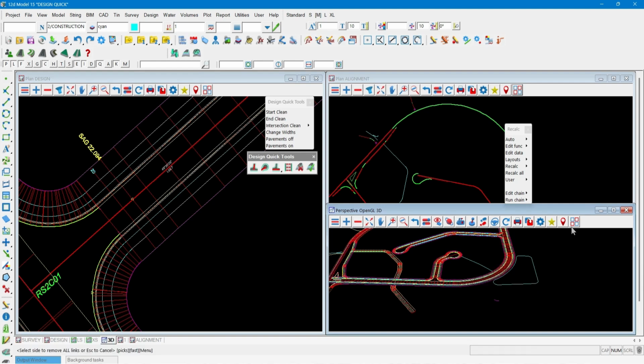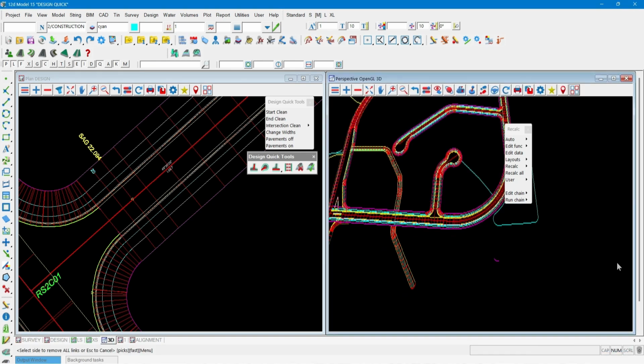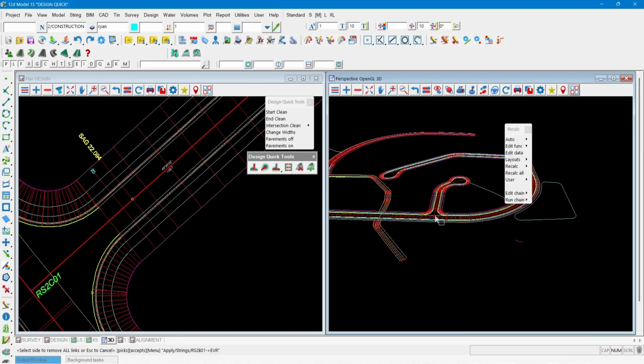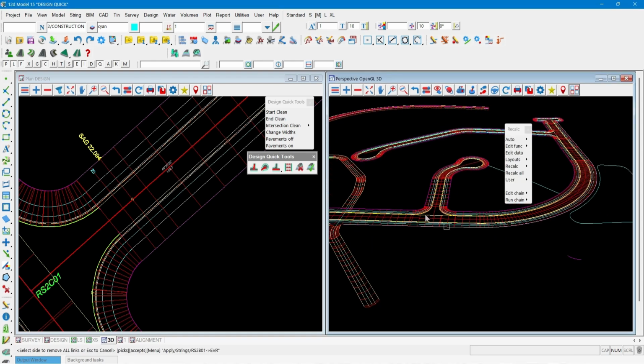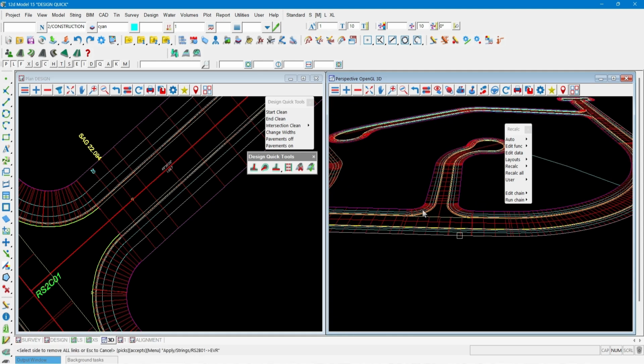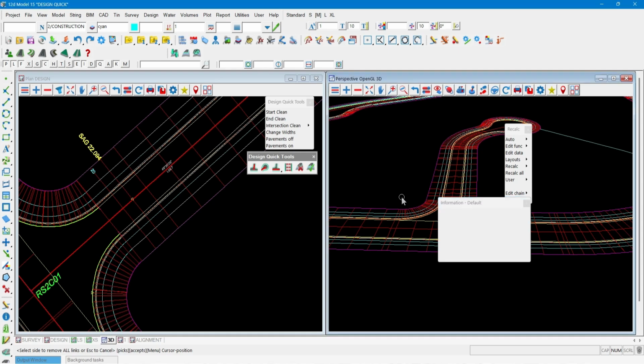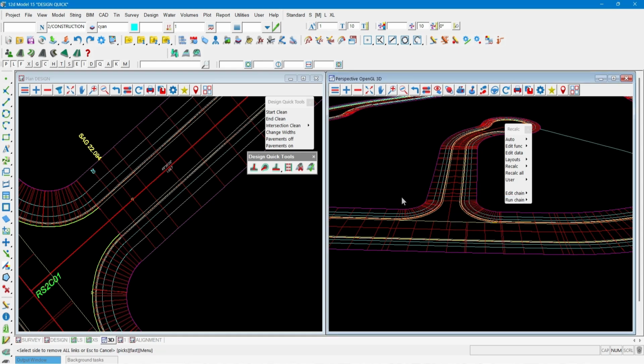And if you have those region names and all of your pavement commands underneath those specified region names that I described in the rules, this is where you can use the pavements on and pavements off option. And it will just turn on or activate all of the commands within that region, or turn off or deactivate all the commands within that region. So I'm going to turn the pavements on for this fun road design, and then we'll have a look at the models that it creates.